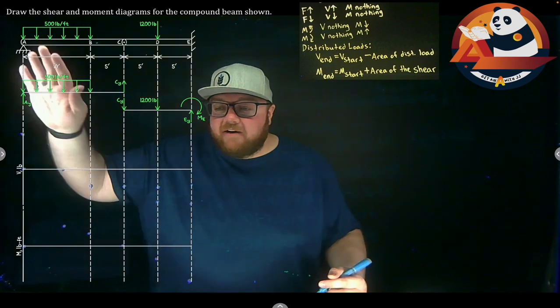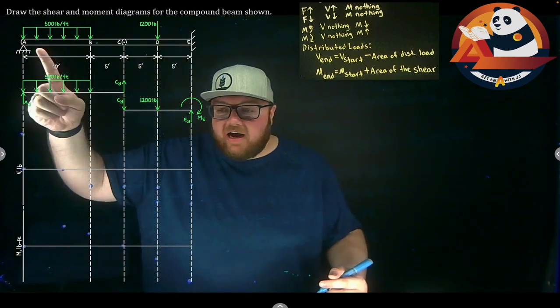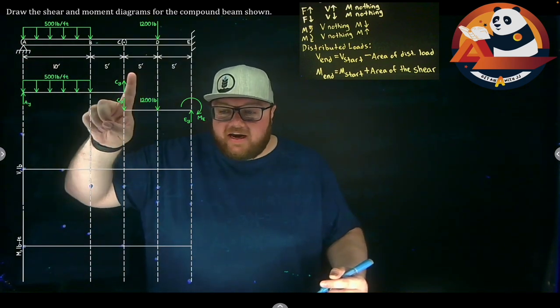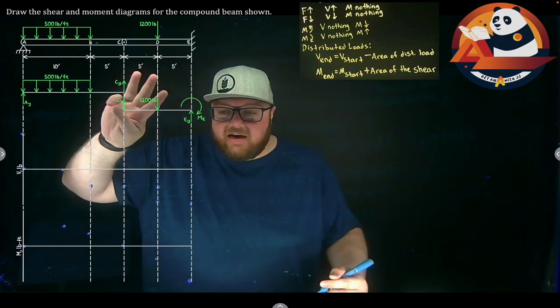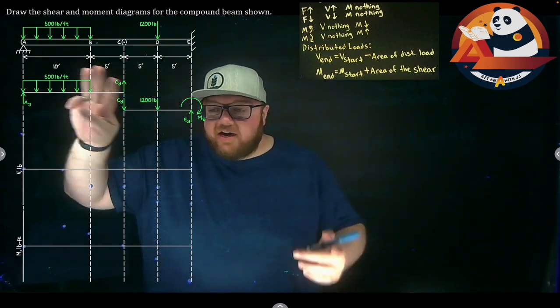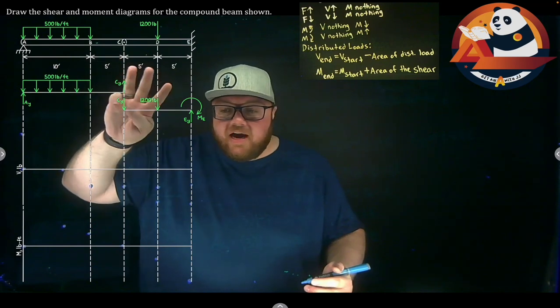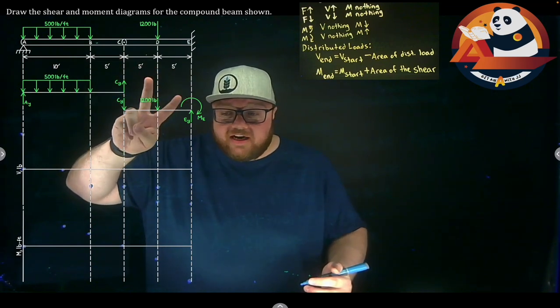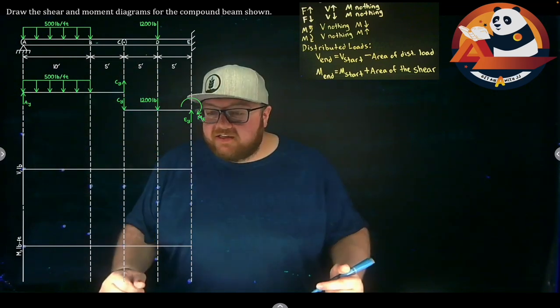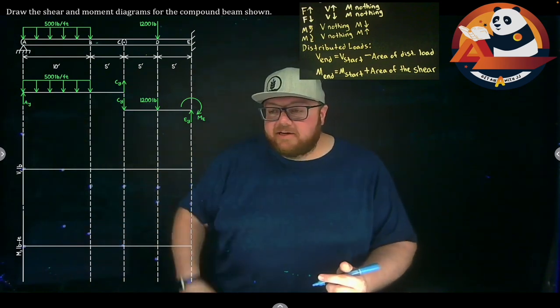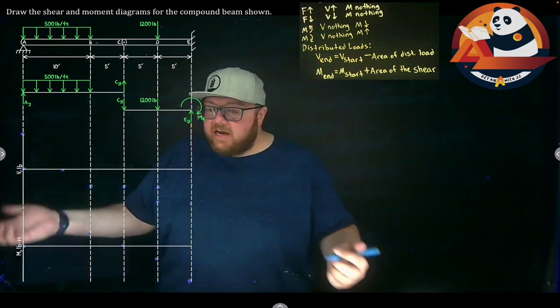But if we were to try to find our free body diagram of the entire thing, I would have, even ignoring the X components, AY, EY, and ME. The X equations, we can't count because we're ignoring those. I'd have three unknowns there and two equations I could work with. I can't solve that out using statics. This is statically indeterminate. Instead, I have to explode this and treat it like a frame.